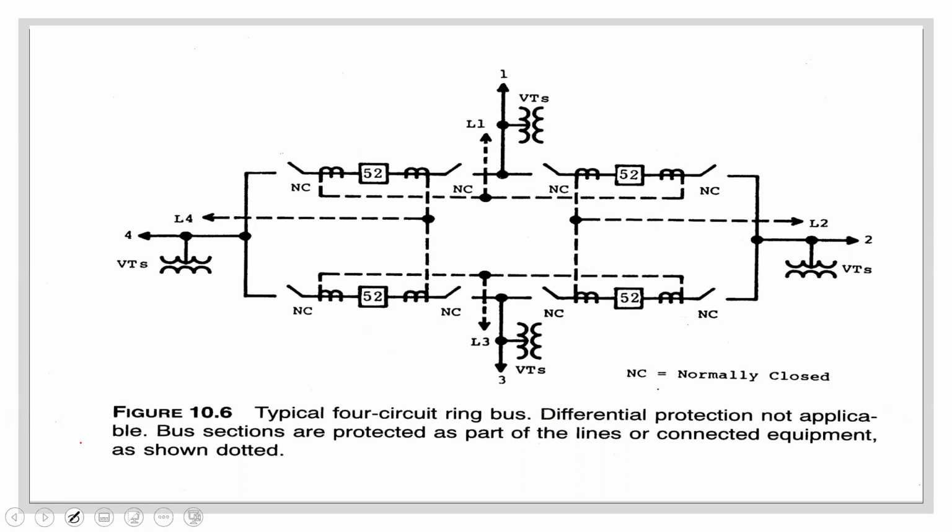If we take out any breaker, let us say I take out this breaker, you realize that I am still being supplied. All 4 loads will still be supplied, because I take that out, everything else is connected. So all 4 loads will be supplied just the same. The only problem is I can't apply differential protection to this, which is a major problem.